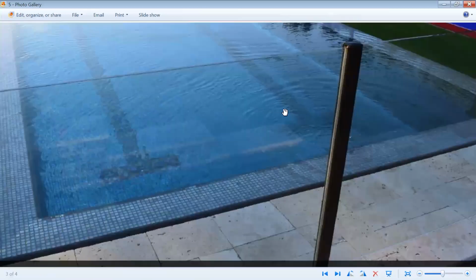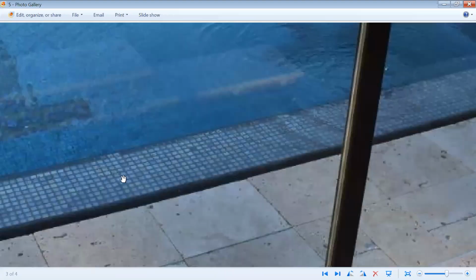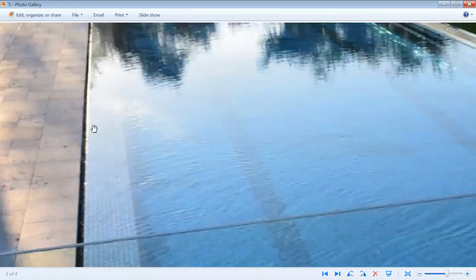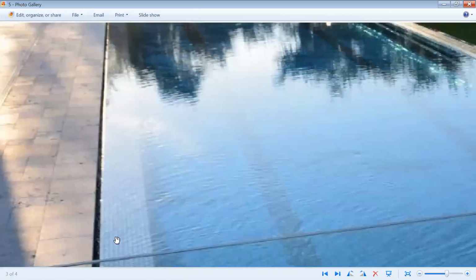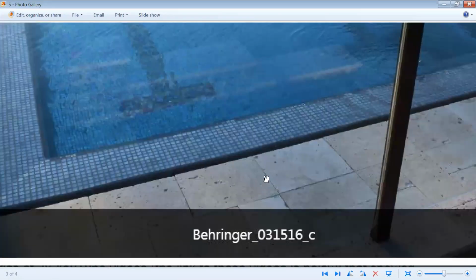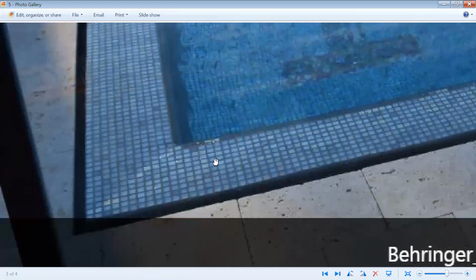And while we see glass tile, that does not necessarily indicate that they just put glass tile onto the concrete or onto the foundation, whatever that was. In this situation, it's concrete, gunite. What happened here is going back to our comment earlier about the travertine or the limestone. They actually used limestone here. So they took large pieces of 24 by 12 limestone, and they allowed for this in construction to actually put the limestone 1 inch thick around this entire edge.